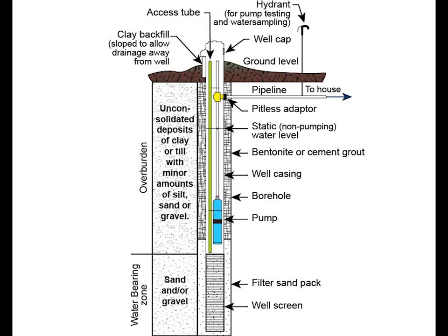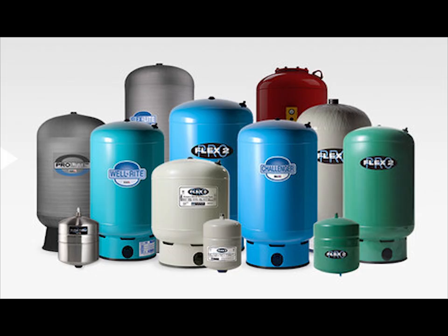Considerations if you have a well. You need to shock your well after placing the pump. You need a water analysis of your well to see what might need to be filtered. I had an existing well that was 50 feet deep with a 20-foot static level, and it gave 16 gallons per minute. Inside the house.